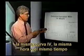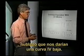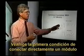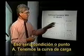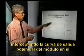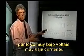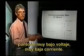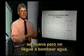Again, we're looking at the same IV curve, the same time of day or the same overcast conditions that would give us a low IV curve. Let's look at the first condition of directly connecting a solar module to, let's say, a DC motor in a water pumping situation. That would be condition A, or point A. We have our motor curve, our load curve, intersecting our module output potential curve at point A. Very low voltage, very low current. This might even be a condition where there's so little current that the pump might simply be moving but not actually even pumping water.